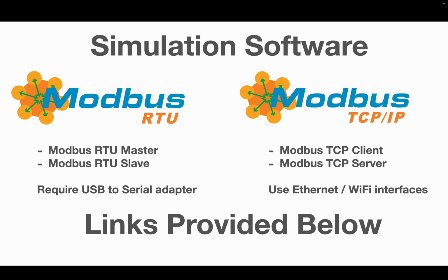So if you are building yourself a device that needs to talk to Modbus devices, you can use the Modbus TCP server to simulate the device from your Modbus client. So typically, if you work with things like an Arduino or other programmable microprocessors that have an Ethernet interface, your device is going to be the client, and the software you need to simulate the other device, the device that sits there, is a TCP server. And on RTU, of course, you need an RTU slave.